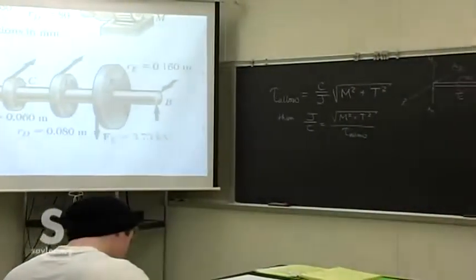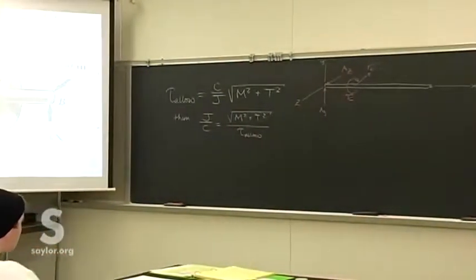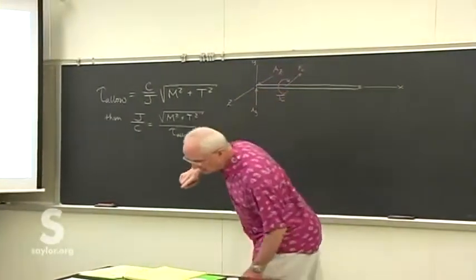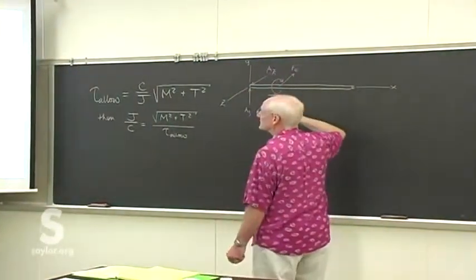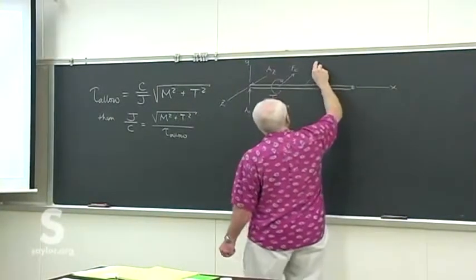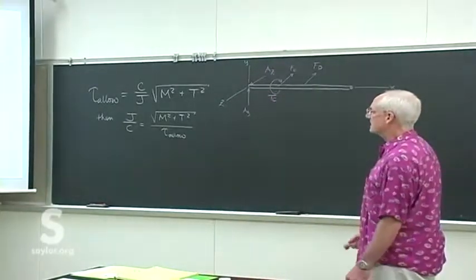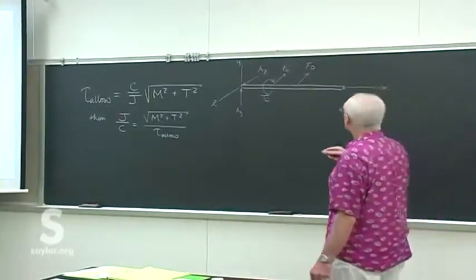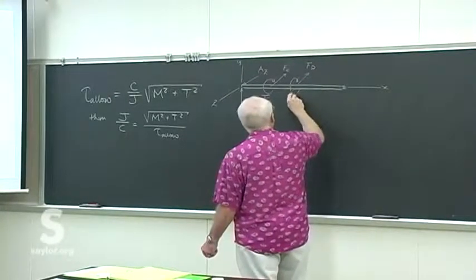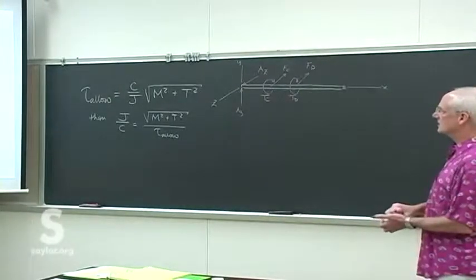So we'll draw it in so it looks something like that. It's fairly easy to figure out what those are equal to when we get the rest of the details in here. Then at point D, we have another force coming off of that gear as we have power takeoff, but that's also applied at a moment arm by the gear size. So there'll be a torsion in the same direction as there was in gear C.